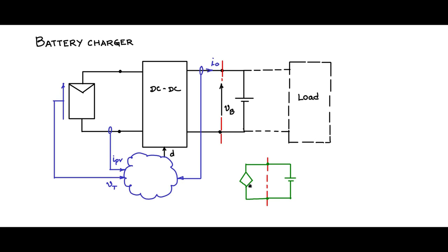If it is a controlled voltage source, plus and minus like this, you cannot parallel two voltage sources because there is no impedance in between, and there can be huge circulating currents which can blow up something in the controlled voltage source. So whenever you have a controlled voltage source, you need to have a series impedance which will limit the current.